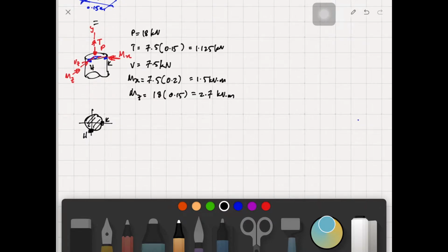And then when we have that r equivalent to 0.03 meter, next we can calculate the area, which is pi r squared, and you can compute this, right? And it comes to the area for this shaft over here as 2.8274 times 10 to the power of -3 square meters.